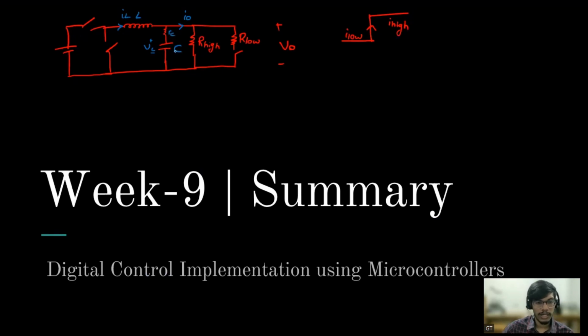We all know that inductor current cannot change rapidly. It has that inertia, because from the dynamics of the inductor, V is equal to L dI by dt, and inductor current cannot change rapidly. There cannot be a step function in the inductor current. So whatever I naught the load is demanding, IL cannot provide, because it needs some time to increase its value. It is a continuous function and it has some dynamics, and according to it, it will take some time.